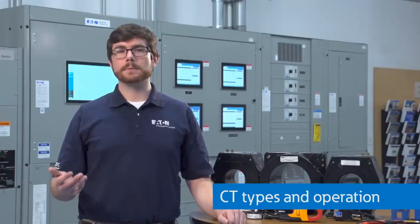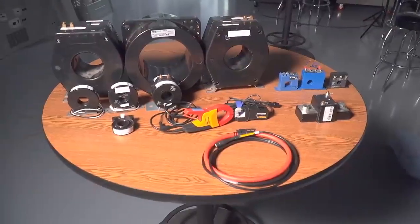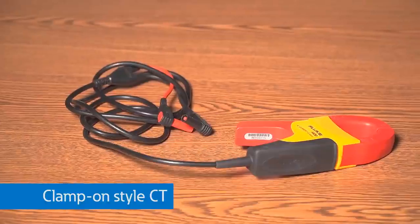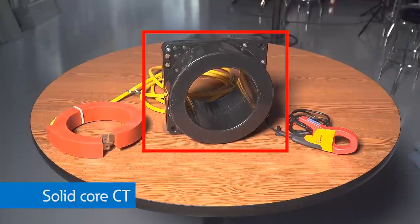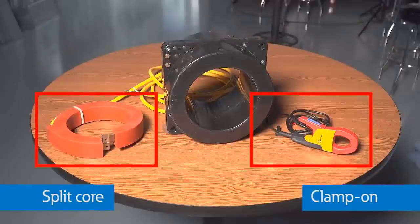Current transformers are primarily used for metering and protection applications and come in various sizes, shapes, and ratings. CTs can be solid core, split core, or clamp-on styles for both low voltage and medium voltage applications. Solid core CTs are generally more permanent and are most commonly found for metering and protection in switchboards, panel boards, and switchgear. Split core and clamp-on CTs are generally used in more temporary applications such as power quality instrumentation.